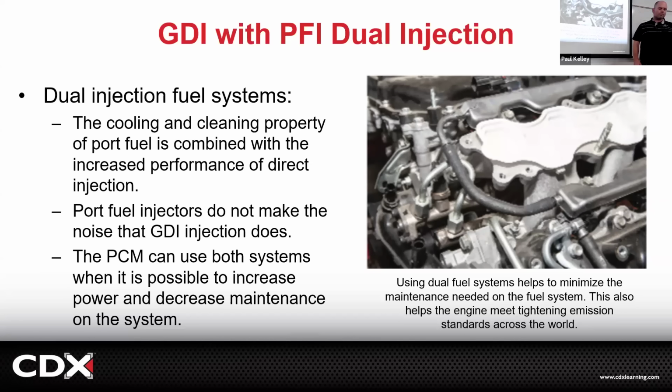Here's a crazy thing about one of these. Recently, a former student who graduated from here, who owns their own shop in Temecula, had a customer come in. Actually, it's in Murrieta, but it's right on the border. Customer came in. Concern was a misfire. Did some of the initial checks. Spark test good. Moved the coil just for the heck of it. Didn't follow. So we know what's on that cylinder. Let's say it's cylinder 2. I actually don't know which cylinder it was. But okay, that's good. Check compression. Compression's good.